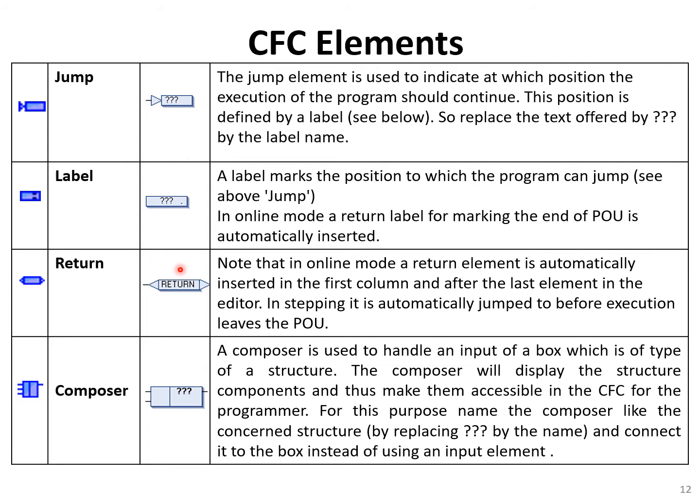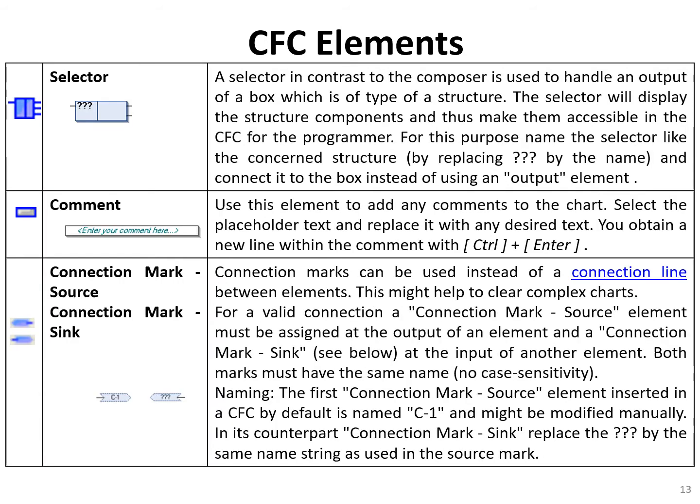Composer is used to handle an input of a box, which is of type structure. The composer will display the structure components and thus make them accessible in the CFC for the programming. For this purpose, name the composer like the concerned structure by replacing three question marks by the name and connect it to the box instead of using an input element. We'll have an example of this composer in coming slides.